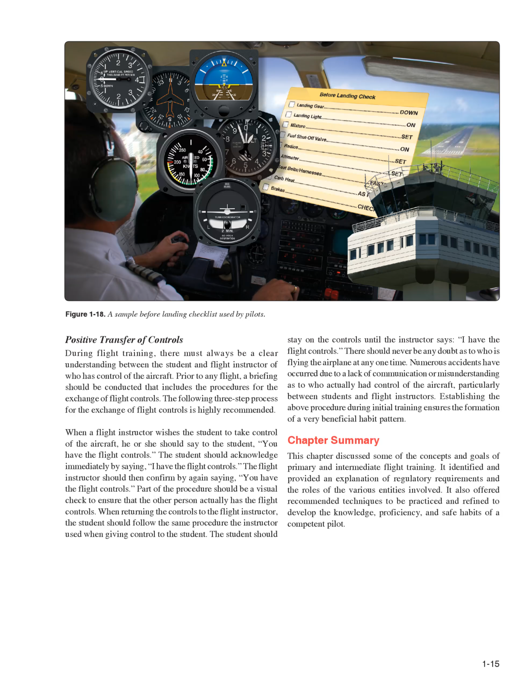Positive transfer of controls during flight training. There must always be a clear understanding between the student and flight instructor of who has control of the aircraft. Prior to any flight, a briefing should be conducted that includes the procedures for the exchange of flight controls. The following three-step process for the exchange of flight controls is highly recommended. When a flight instructor wishes the student to take control of the aircraft, he or she